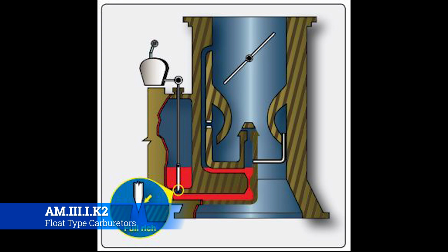So the way that happens, there's a red handle inside of the cockpit that slides forward or backwards or in or out, depending on the style of handle that's there. That goes through a series of linkages that actually moves the needle in or out of the carburetor. Now that needle will open or close this little orifice that allows different amounts of fuel into the carburetor itself. Either A, it opens up wide and lets a lot of fuel in to enrich the mixture, or B, you can cut off the engine by simply pulling the mixture handle back, and the engine will shut off totally. And then you can turn around and feather it one way or the other to get the maximum amount of RPMs that you need for a particular flight configuration at a certain altitude.